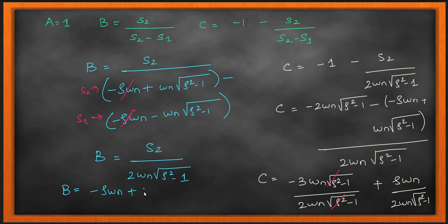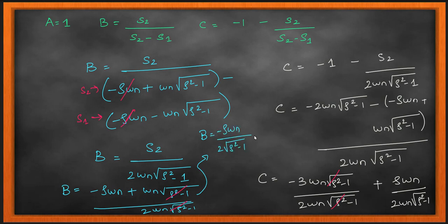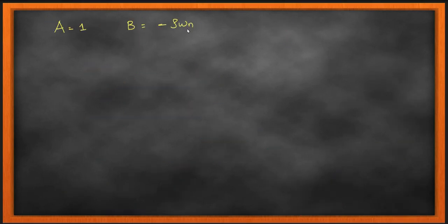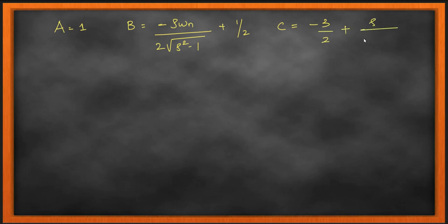So omega n is your natural frequency, and that's not going to change, and your zeta is greater than 1, and that is also not going to change, because when I say greater than 1, it can be any value from 1 to infinity, but that is not a bounded system. So there you have a reason for your system to get unstable or to go out of stability. So I'm just going to say it's greater than 1, but I'm going to stick to a value of 1.2. So it's greater than 1, but it's a fixed value. So whenever your zeta or the damping ratio is fixed for a value greater than 1, then all these things that we are doing could still give you a very stable system.